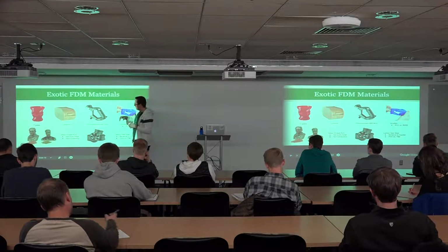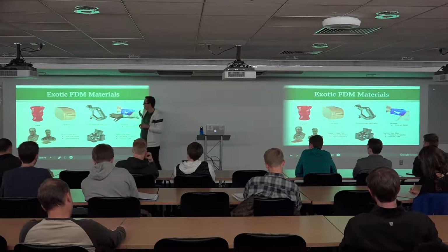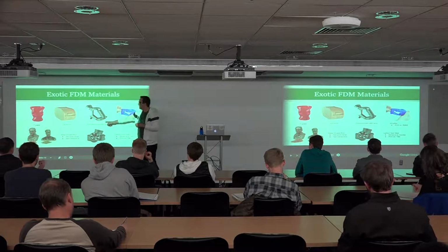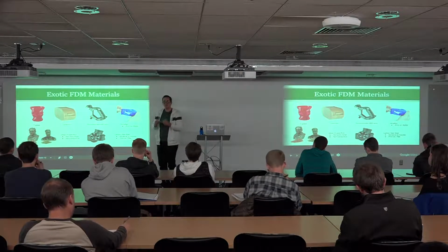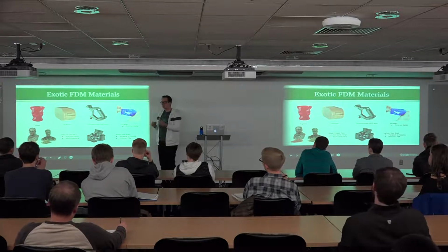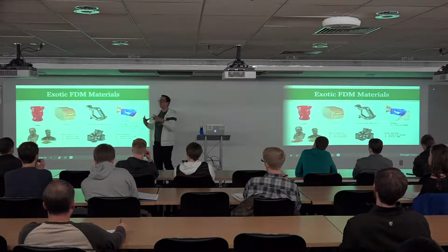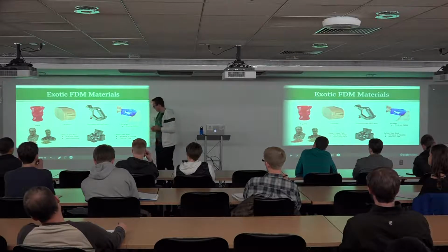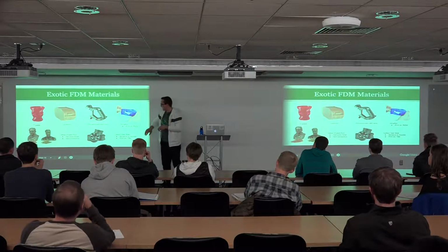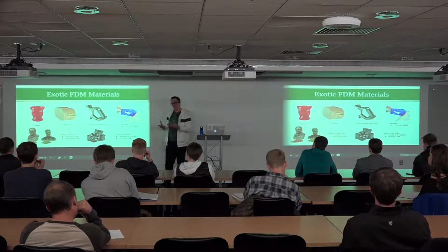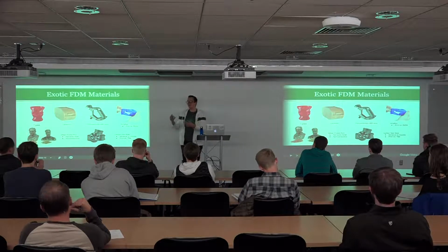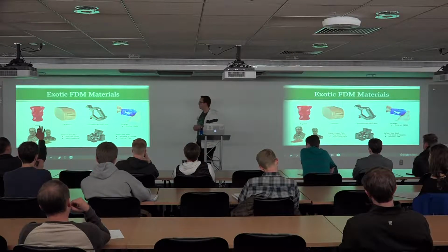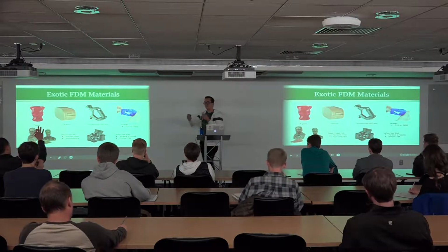And then polycarbonate alloy, or PC ABS. You can get pure polycarbonate as well. It's just a little bit stronger, more impact resistant plastic, but it can be a little more difficult to print with because it contracts even more than ABS does. And then carbon fiber filament is really cool and a little bit stronger than regular filaments, but it is abrasive to the nozzles. So I just put print on to be announced because we have special nozzles ordered to be able to take that kind of abrasiveness and not wear out.